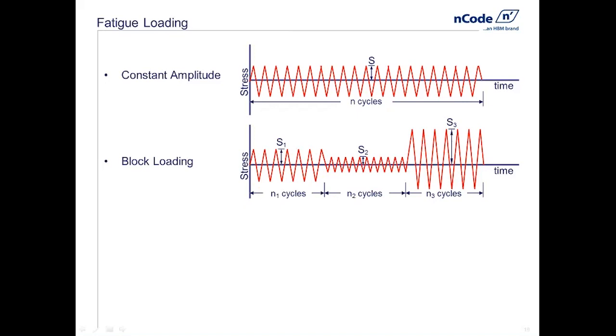This top example might be if you think about, say, a railway application where we have a stress in an axle, and as the axle rotates, it goes through reverse bending. So this is it trundling along down the railroad track that's very smooth, and it's got one static weight it's carrying, which results in a rotating bending scenario.